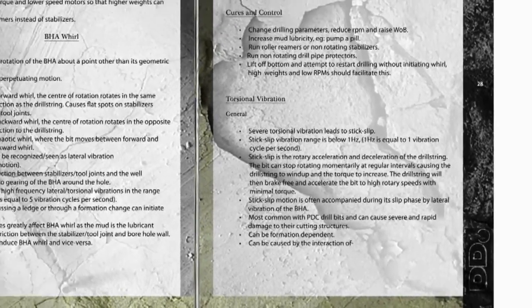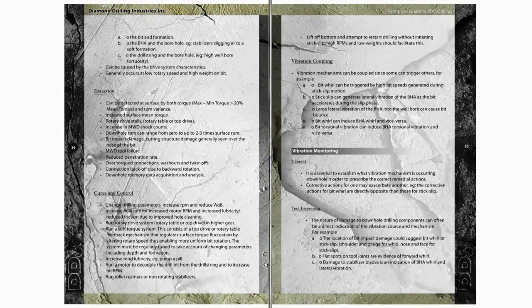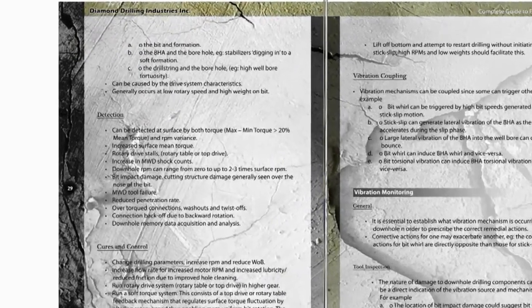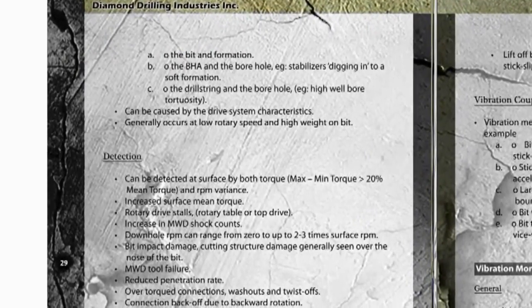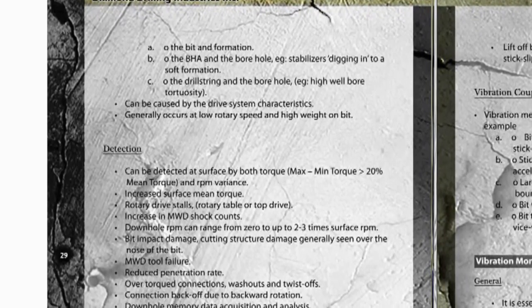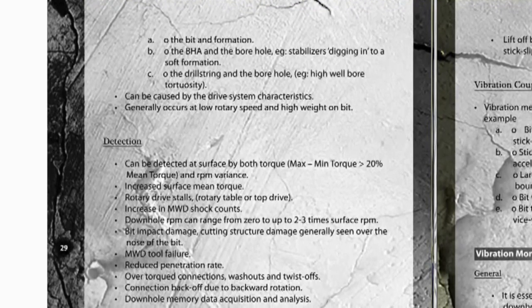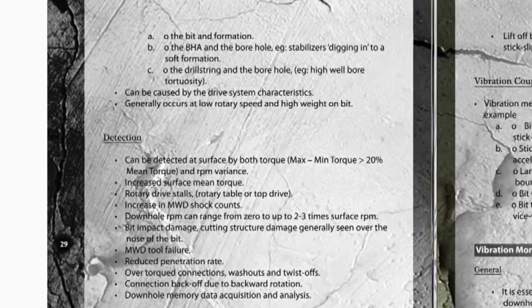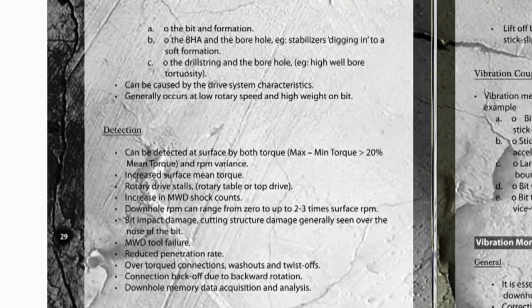Can be formation dependent. Can be caused by the interaction of the bit and formation, the BHA and the borehole, for example, stabilizers digging into a soft formation, the drill string and the borehole, for example, high well bore tortuosity. Can be caused by the drive system characteristics. Generally occurs at low rotary speed and high weight on bit.